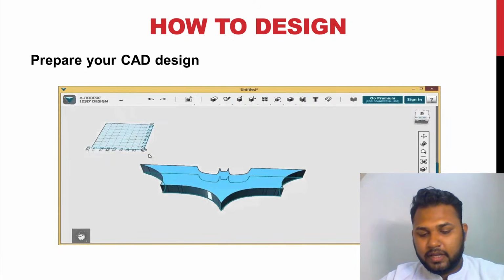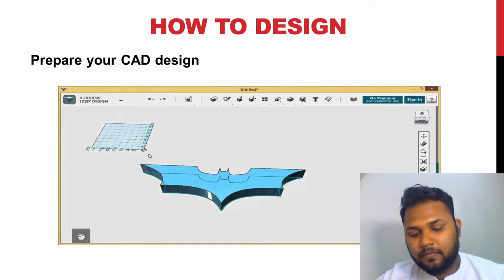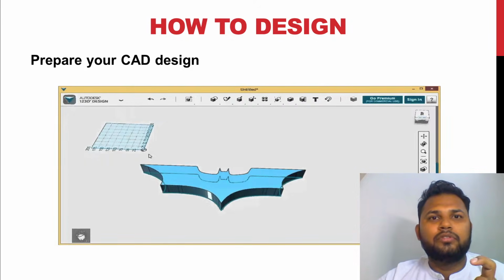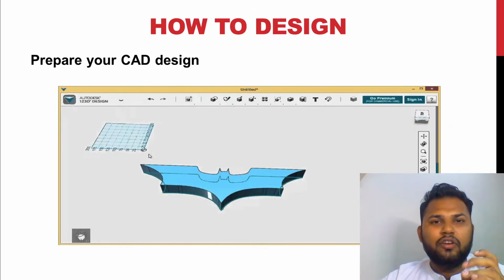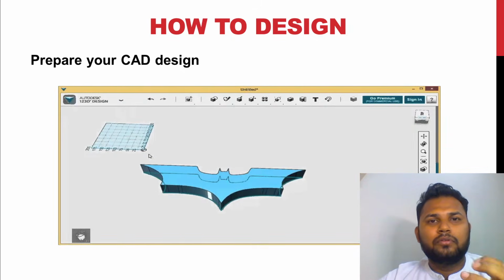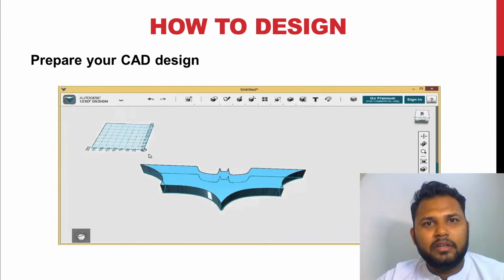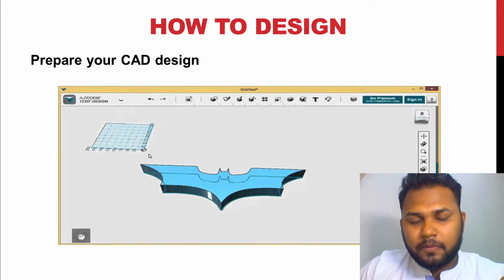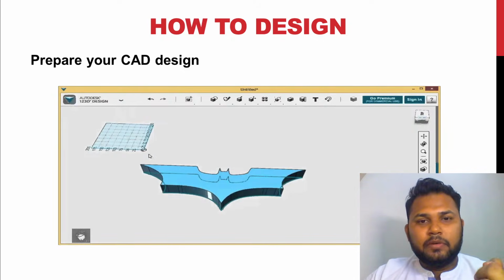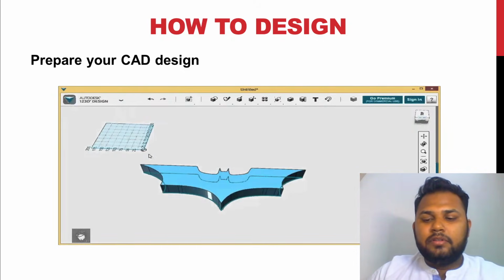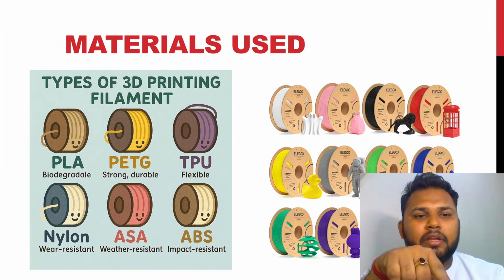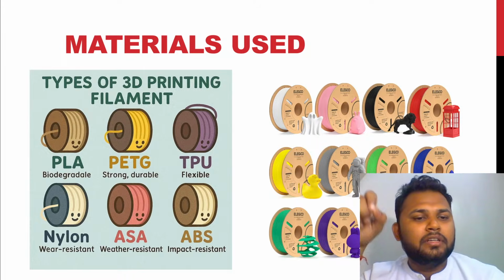Which is the strongest among all? There is a PEEK material in fused deposition because we are talking about the kind of plastic material. So PLA is not that strong a material. Very nice question Divyanshi Pallavi has asked. Which is the strongest material among all of the materials which we have seen? Like in the above given six materials: PLA, PETG, TPU, nylon, ASA, ABS.